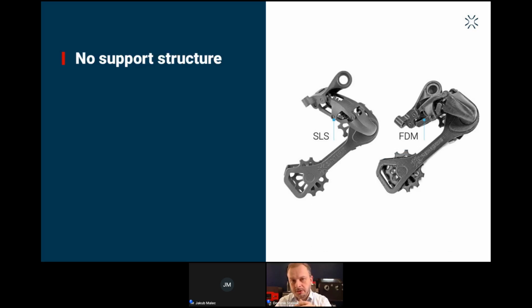I think the most famous feature of SLS technology is the lack of supports. You don't need any supports when you are creating objects. This translates into a very important feature: when you are thinking about placing your models in the build chamber, you need to think about it fully in 3 dimensions. You don't use only the print bed, but the full print volume.